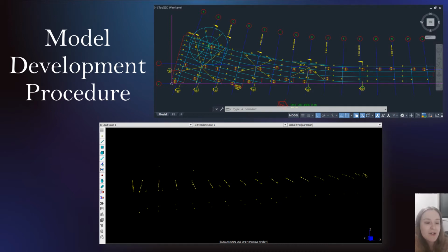The magenta lines drawn onto the roof steelwork DWG showed the X and Y axes, and the white circle the reference point. A similar reference point was used for the footing plan with the same X and Y coordinates of 0. Measurements were taken from this reference point to the columns to find the coordinates for the base of the columns. For the top of the columns, the height of the columns was measured from the elevations plan. To ensure continuity of the column from the base, the gradient of the column was calculated and used to calculate the position of the 3 columns that extend past roof level. These nodal coordinates were entered into Strand 7 to develop a nodal map.